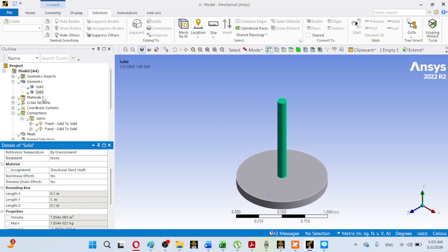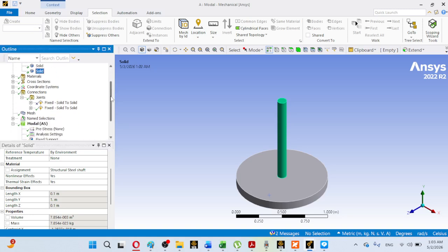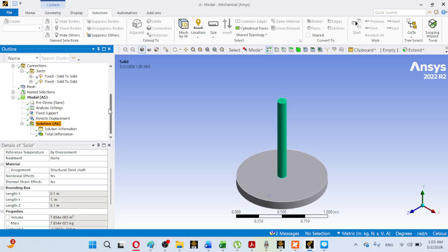And so two materials were created, and furthermore a fixed joint was used. This fixed joint was actually suppressed later, because it was created for the different geometry, meaning for line bodies for example. So the final geometry was shown here as a fixed joint solid to solid, meaning both were the extruded model as listed here. So I am just summarizing what was done in the previous lab session.